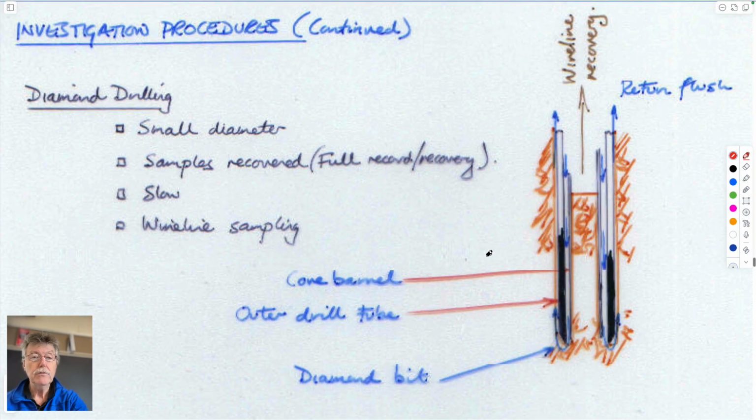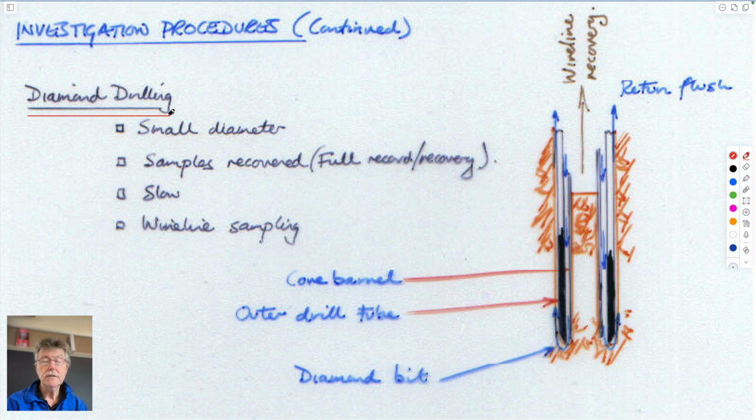And then there is rotary drilling. Some rotary drilling is sometimes also called diamond drilling, not drilling for diamonds. But the idea is that this is just a tube. So this is just a cross section through it. It's a tube that has industrial diamonds on the tip, around the rim of this.